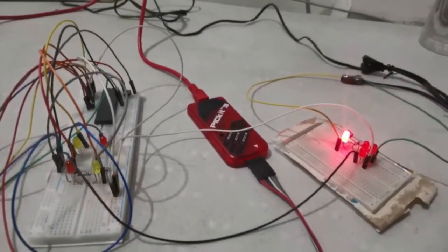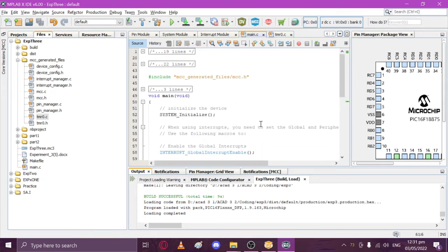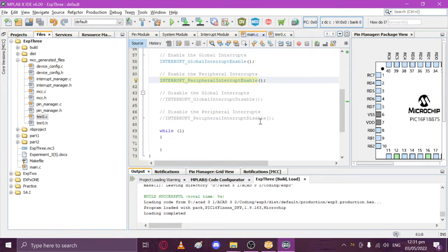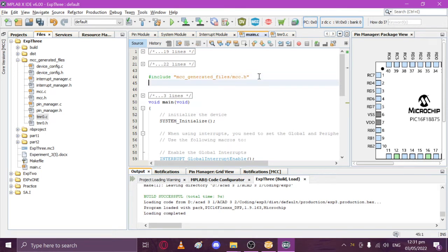So going on over our code. So here we are back again with our code. This time we need to have it set off at an interval of 2 seconds. In order to do that, I will make in the main a variable named PSD, just like on the previous one, but I'm gonna declare it as a volatile integer PSD and define it as 0.